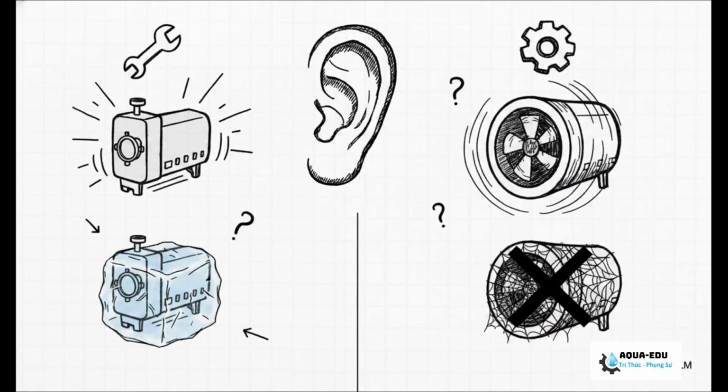Okay, now let's talk about what you're actually going to physically see and hear when you're out on the floor. You might be walking by and hear your chemical dosing pumps operating continuously without a single pause. Or on the flip side, freezing up entirely when they absolutely should be running. You might also hear your massive aeration blowers maxing out at full speed or just stopping dead in their tracks, all because they are no longer adjusting to the actual dissolved oxygen load in the water.